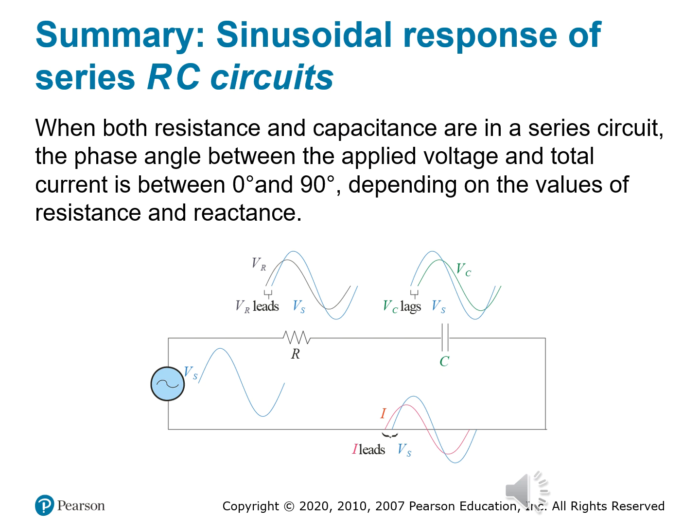It depends on the ratio. The amount of lead depends on the relative values of R and X sub C, and that's right, the capacitive reactance X sub C being equal to 1 over 2 pi FC plays a big role here.